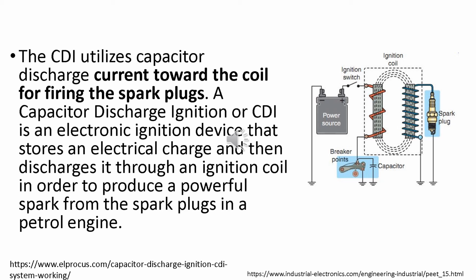Next is the application of capacitors in the motor engine. CDI, or capacitor discharge ignition, is used to store electrical charge and make an ignition. To have ignition, the engine needs to produce a powerful spark in the spark plugs, and that is when the motor is turned on.